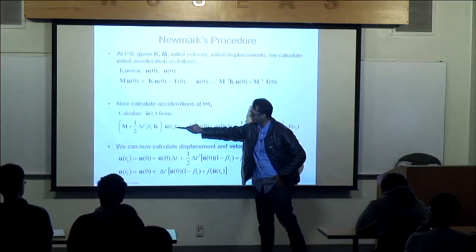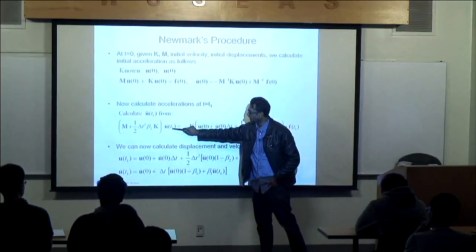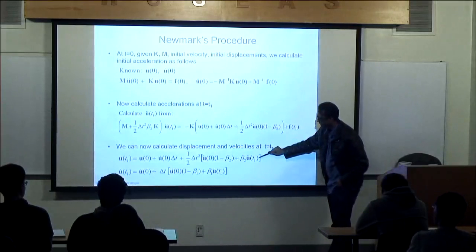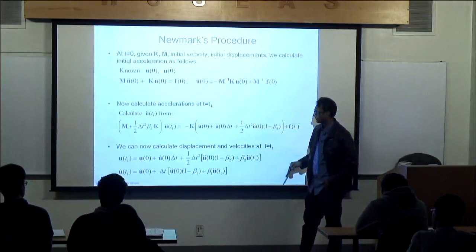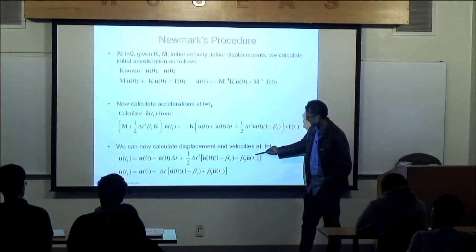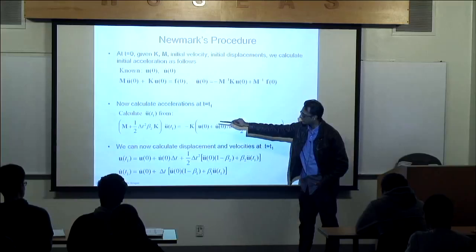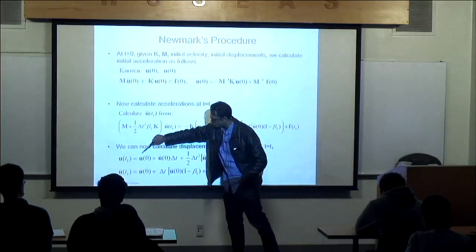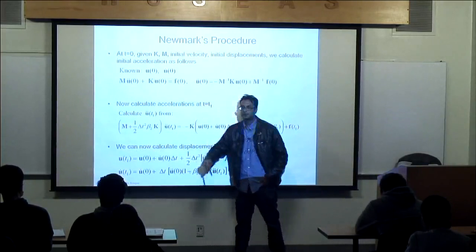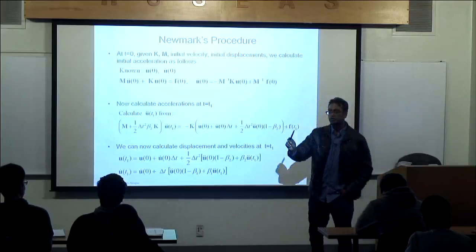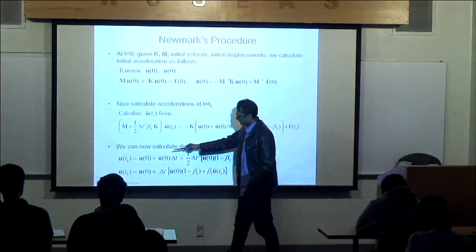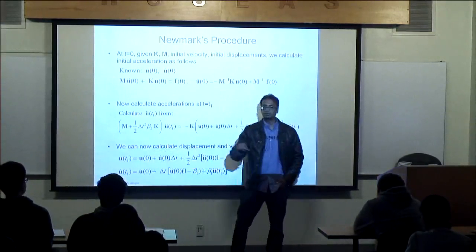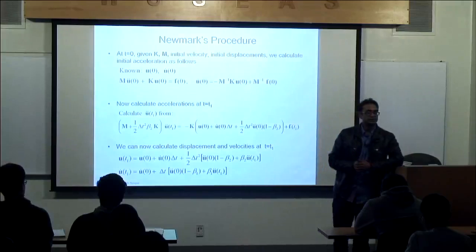If I have the accelerations in the future at t equals t1, with that information, I can plug that in here again into my formula for u bold that we had earlier. And if I know acceleration in the future, I plug it in here. I know the acceleration right now. I know the velocity right now. I know the displacement right now. I have the displacements that correspond to t equals t1. Not only that, if I have the acceleration, again, I have the velocity at t equals t1. You agree with what I've just said?